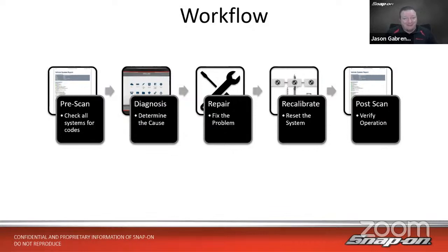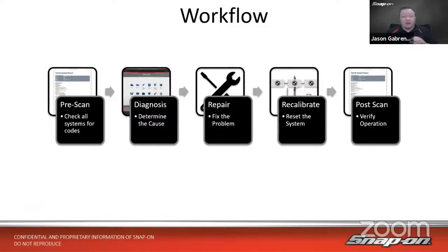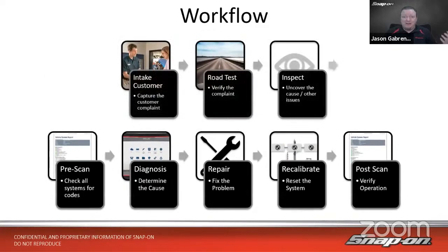Now, hopefully, if we have a car that started with no codes in the pre-scan, we don't have any codes left in the post-scan. But hey, things happen, right? Sometimes things get left loose or what have you. Maybe a new problem generates itself. So we always want to make sure we have that post-scan so we can return that car back to the customer in a way that's hopefully better than when they brought it in. But to add to that, we have to do some things before we get to this point, don't we? And I think when it comes to no-code diagnostics, really the most critical is going to be this first one here, the customer intake process.